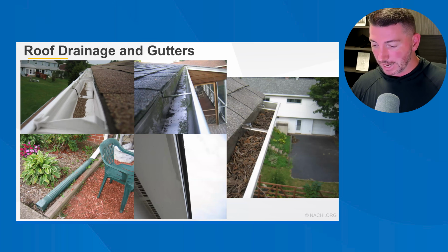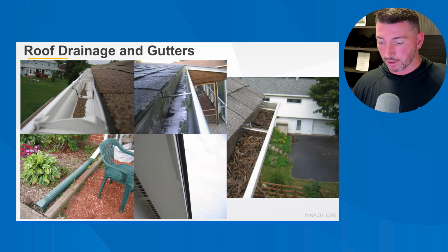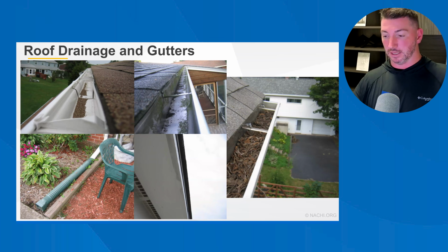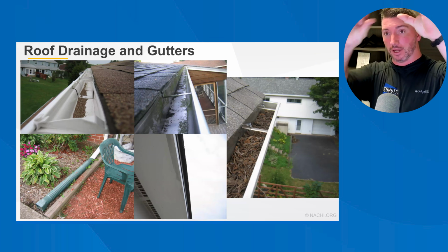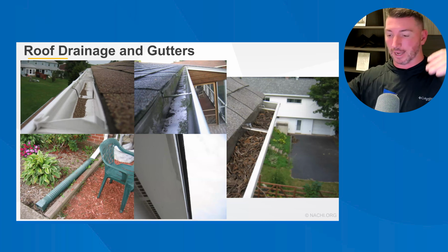So in judging adequate slope, look for signs of standing water in portions of the gutter away from the downspout and eyeball the margin against the fascia. That's one good tip: look how much of the fascia is exposed at one side of the gutter, and then it will slowly disappear towards the high side, right?